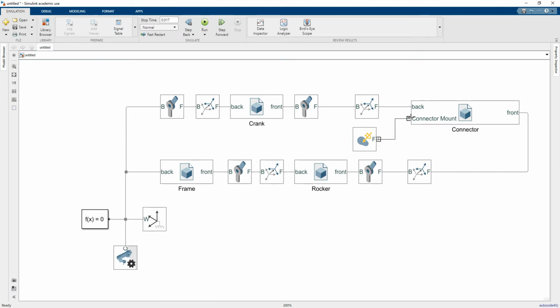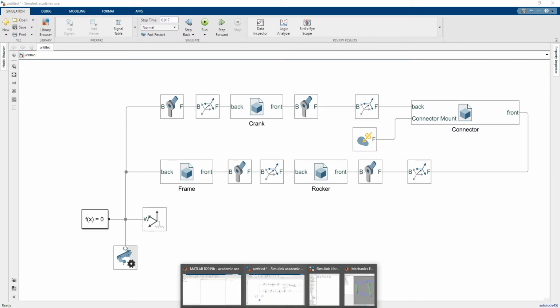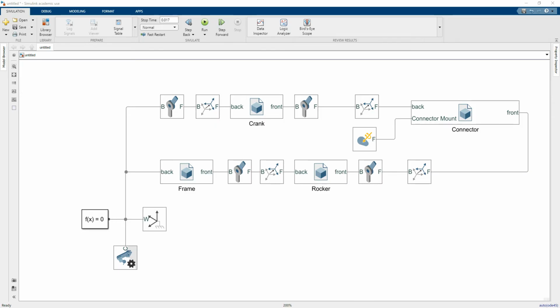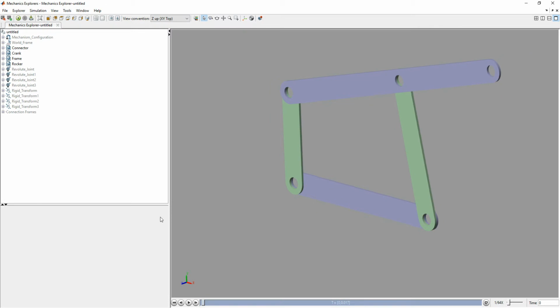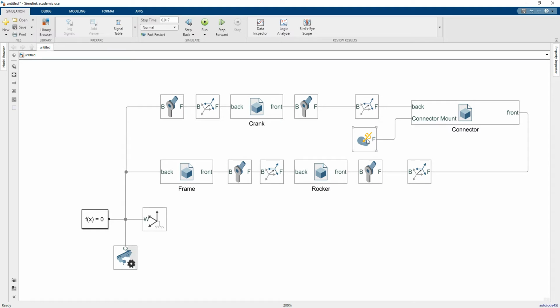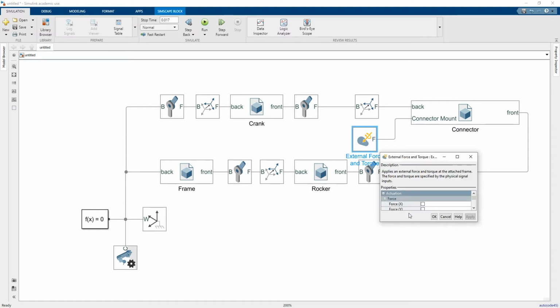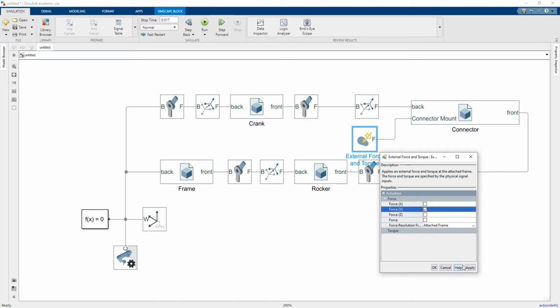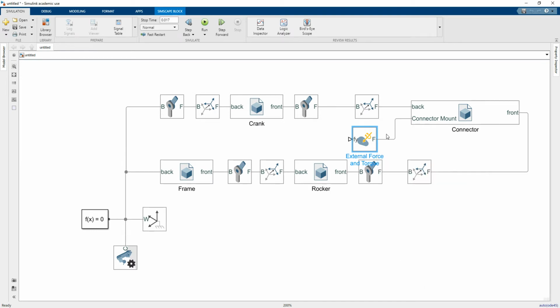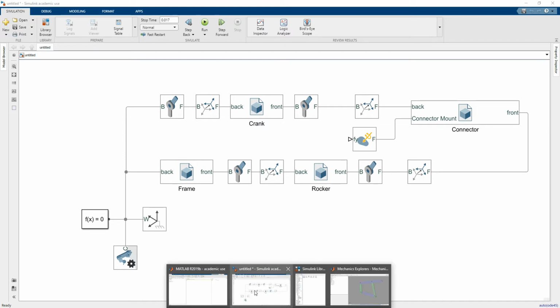I love this. So I'm going to tab that in. The reason I've been jabbering on, and I know I jabber, about gravity, knowing where everything's sitting, is we need to know where our gravity sits, because we need to know what direction the connector is holding on to it. So I'm going to double click in, I'm going to go force, and I'm going to go Y. So apply force in the Y component. Now it says, okay, you've got that force there. Now what do you want to do? Now we're going to have to drive it with something.